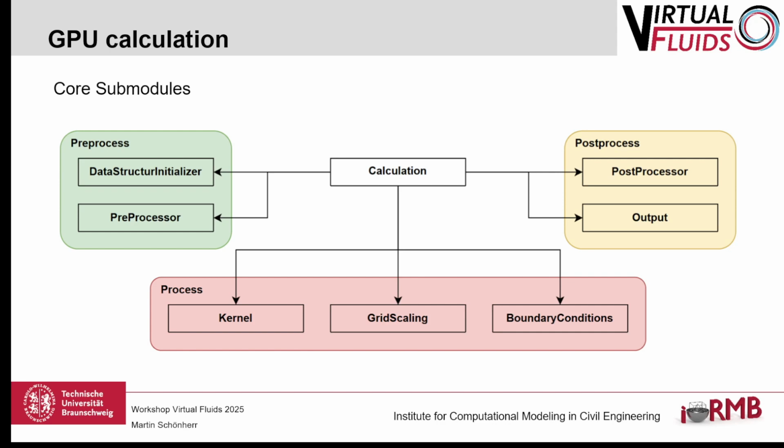They need maybe days for a grid generation, but for Lattice-Boltzmann this is a long time, and you want to do a convergence study, for example. So you want to run it again and again, and you don't want to create the grid new all the time because it's always the same. Then you can store the grid and read in this grid just from a file. So this is decided here. You have to say if you want to read in or generate the grid.